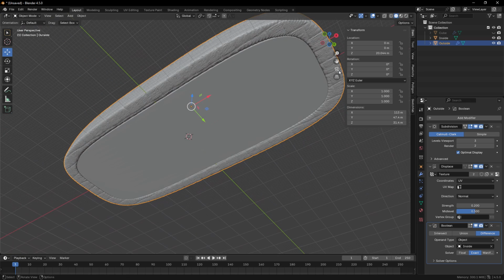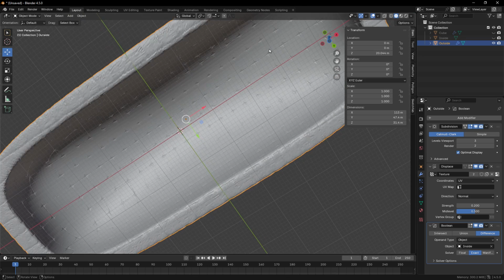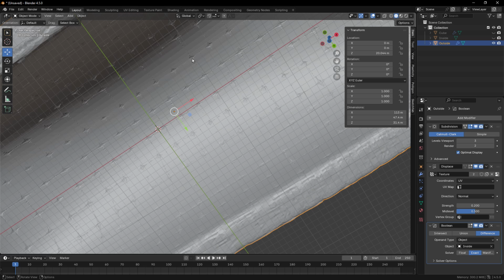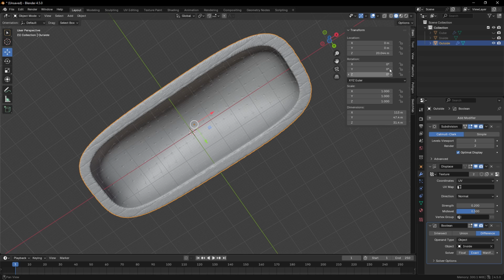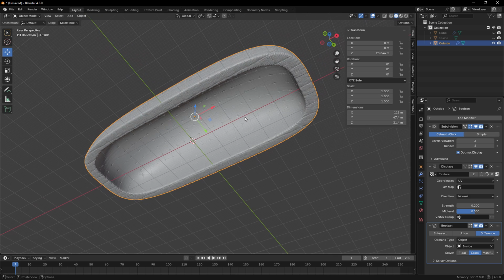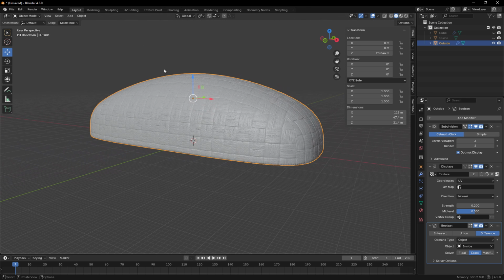All right, so now if I hide the inside, you can see that the inside has removed that carbon fiber texture, but because of the areas that were lower, you can actually see what's happened is those are still there. It's got the kind of weird texture to it. So what you could do is you could scale up the inside, or you could scale down the inside of this part before you do the subtraction. Now the bottom didn't get subtracted because we didn't actually have anything there. So the easy way to do that is